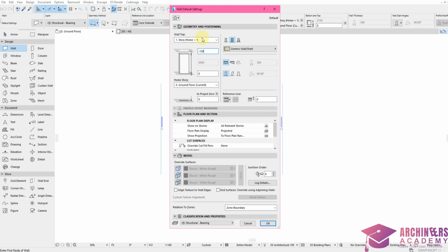Then the next thing I do after fixing my wall height is to come over here to the structure of the wall: basic, composite, or complex profile. I will change it to what? Basic. I'm going to make use of basic wall, which is the frequently found wall around us. Then this is now the width of the wall. Different countries make use of different wall sizes, so you can choose to use the wall sizes that suit you. So I'm going to make use of 225 thickness of wall. Then I'll make sure that this is on straight. It's not a slanted or double slanted wall.